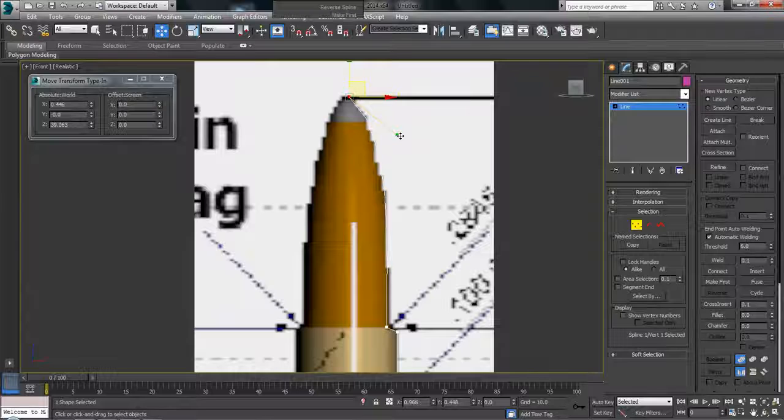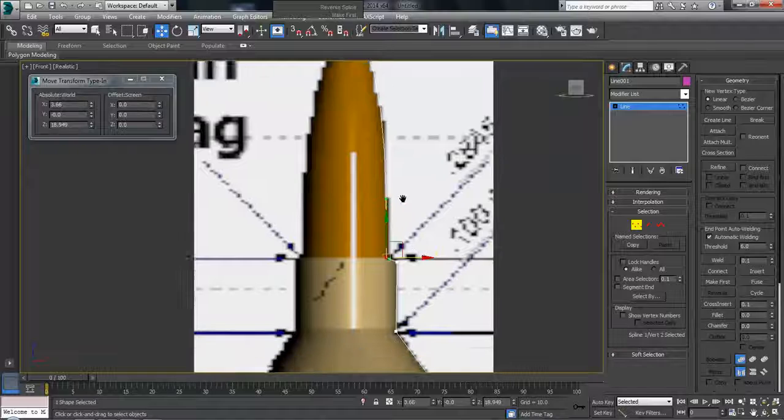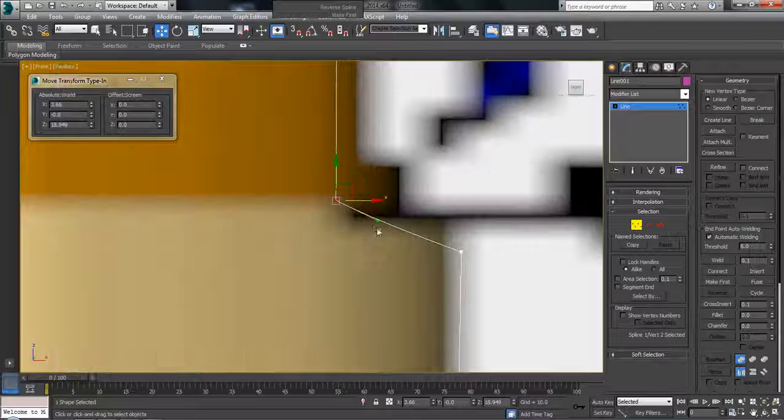This image is not the highest quality of image, but for our purposes now it'll serve okay. So there's the curve for our round coming down. I'm going to make sure that this one here, where the line enters this one, it's straight down. I'll come down here and I'll take a look at these vertices here, and I'm just going to make this straight. You might be able to pick it up in the viewport there. You can feel it snap to a straight line.